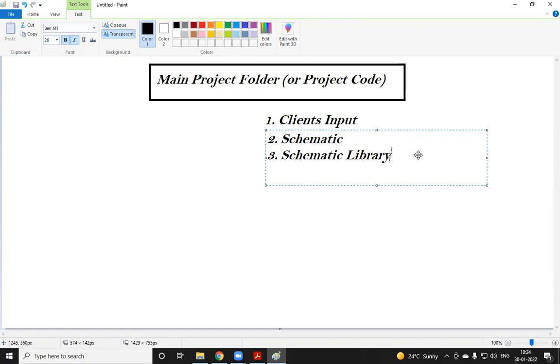If you find some errors and warnings, you can't easily get rid of them. So I always suggest you create your own schematic libraries, so that the practice will be proper, and whatever mistakes, errors and warnings you find, you can easily understand and clear during the design life cycle.